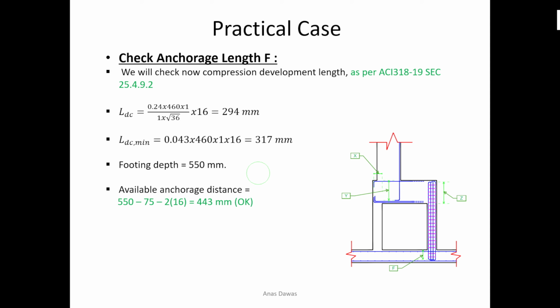Okay. At point F, this is very important, inside the footing. We said before that the minimum anchorage requirements may govern the depth of the footing, not shear only.